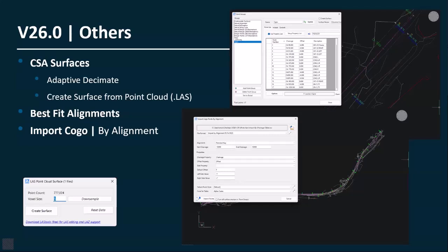So they're the three tools I'd like to show. I will just make a note, even though there's not a bullet point. If you do start a project from a Stringer command that's not import and reduce, we don't automatically pack the data inside the drawing. There's an option for you to do that, but it's defaulted off, so you can tick it on if you'd like to embed the data inside the drawing.